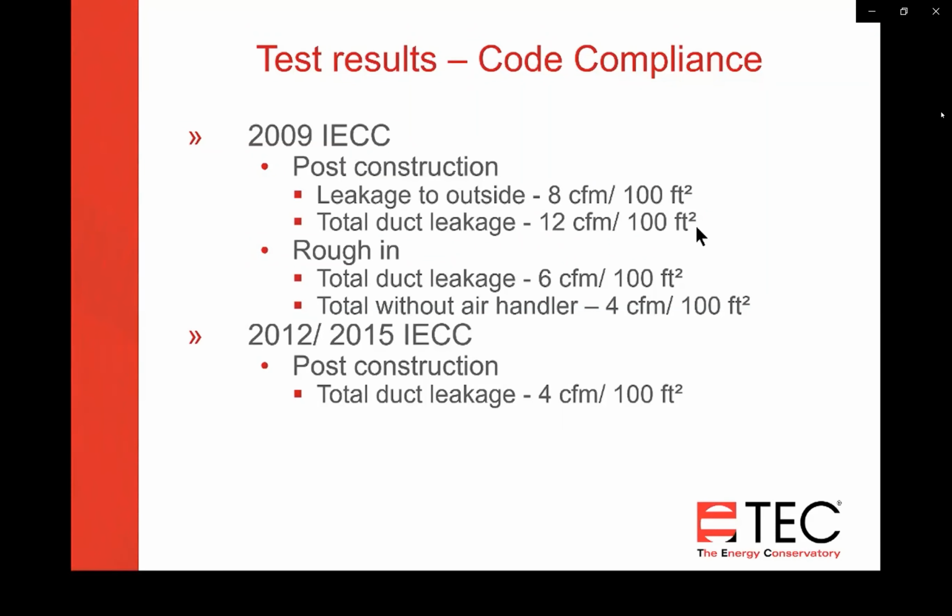So then you'll put it up in one piece rather than doing it as you go along. So some of the, physically how you put the systems together and put them in changes also. So you're not blindly trying to seal the ductwork. You're sealing it when everything is visible and readily available, and then you can get all of it sealed really well.